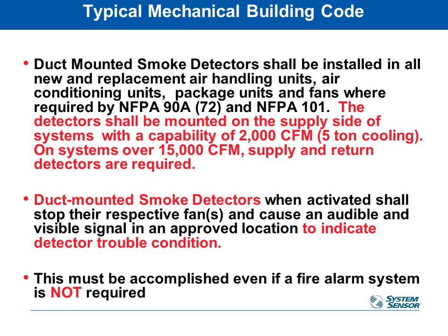And then the main goal of these duct smoke detectors, like I said, is to sense the smoke in the duct and prevent that smoke from circulating through the building, or prevent new oxygen from being brought into the building to provide oxygen to a fire that's already burning. So the way that we prevent that from happening is by shutting down the supply fan, return fan, and exhaust fan associated with that rooftop or air handler. So once the detector detects smoke, then it disables the power to those fan systems inside the air handler.